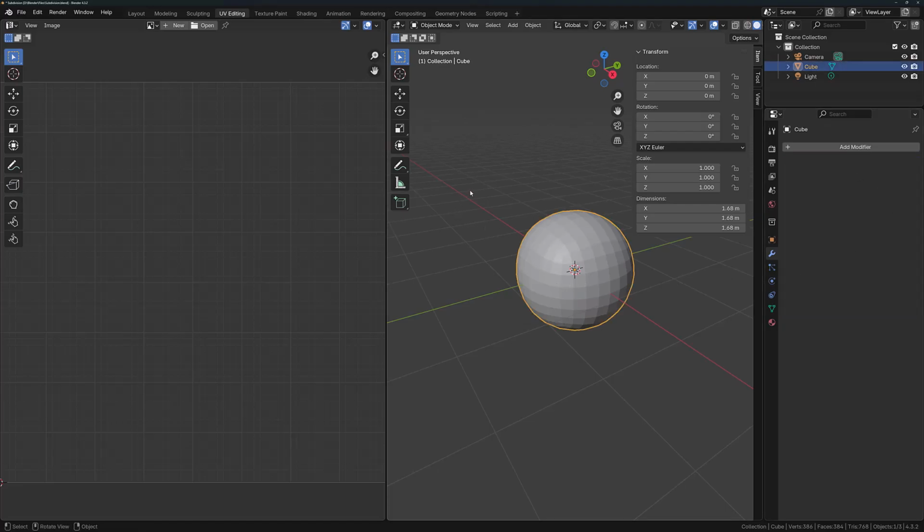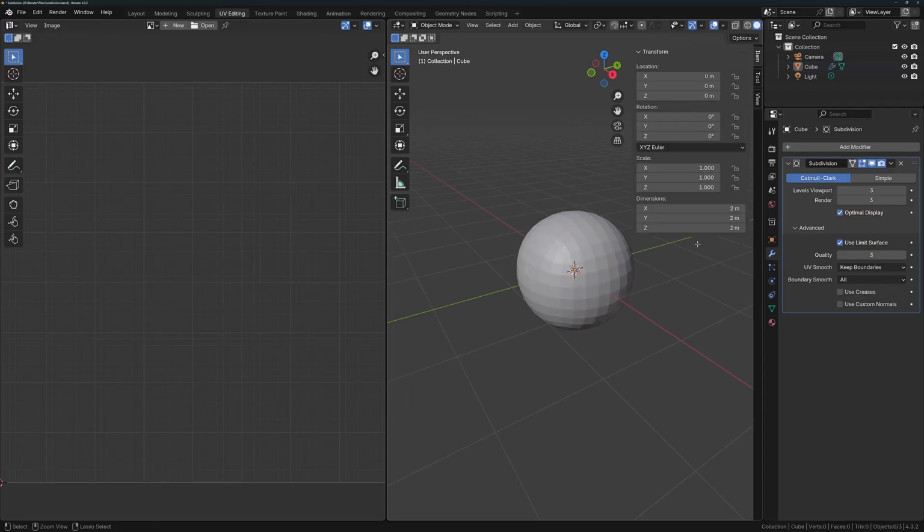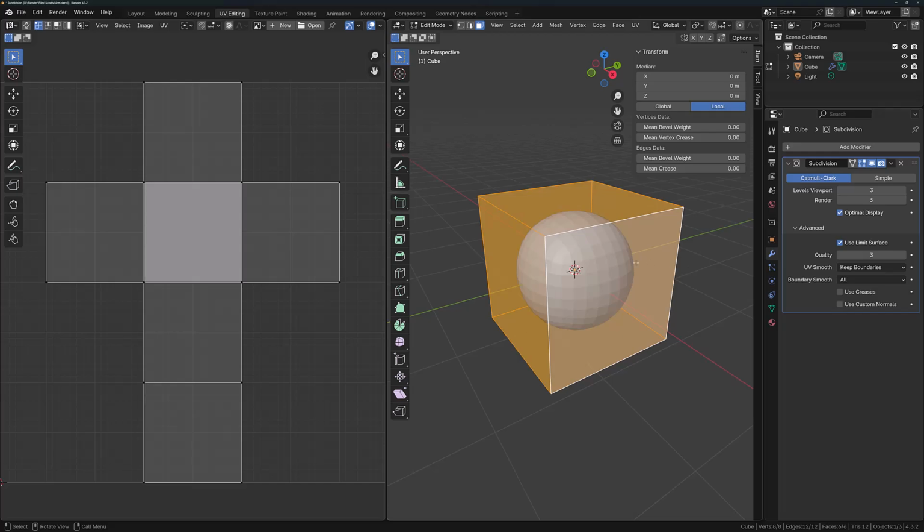We're going to select the model, return to the UV map in edit mode, and you can see all of the geometry that has been added in edit mode. So this is perfect, but what happens if we were to change that UV smooth option? I'm going to hit Ctrl-Z a few times until I return to the UV map in edit mode again.